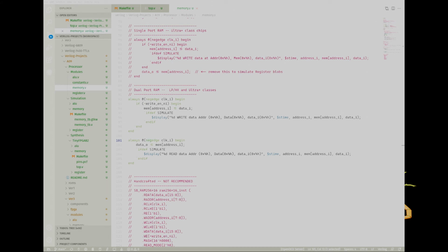And again, if we look at nextpnr, it should show us the same utilization as before. So if we search for device, you can see that it's identified one usage of the iCE40 RAM. We just learned how to check the results of the inference, but can we specify exactly what we want and skip the inference? Yes, but I wouldn't recommend it. However, you can find out how to handcraft your memory by checking the spec sheets of the system section.